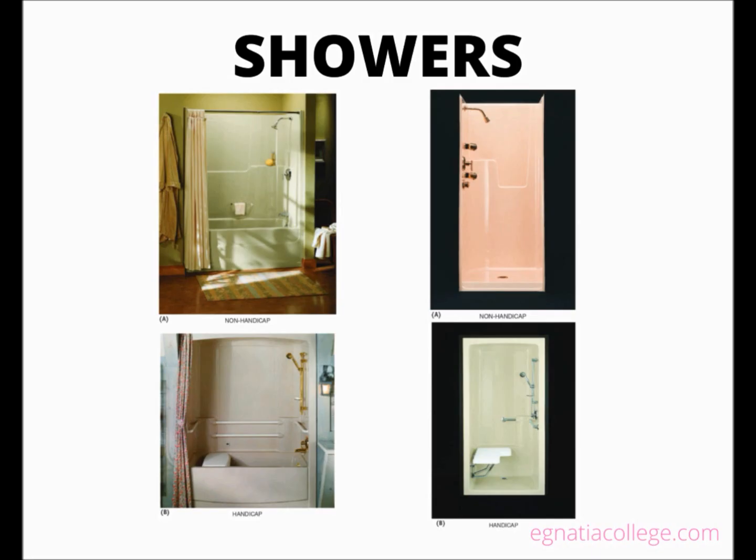A tiled shower base installed on a wood floor must have a safety pan installed before the tile is placed. A plumber usually installs the safety pan. The most common safety pan is PVC liner material sold in 4 feet and 6 feet widths and in custom lengths. Many handicapped showers have a factory-installed folding seat.